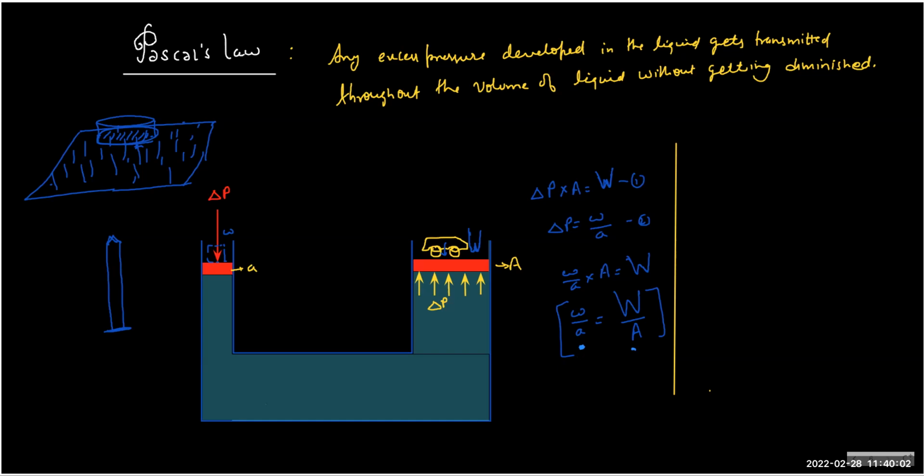It is very dangerous. In a pressure cooker, earlier there used to be a very large number of accidents. So later on, the safety valve was introduced. And what is the safety valve in a pressure cooker? Something like, you can see a hexagonal patch, and this part is very weakly welded with the lid actually. So if the pressure exceeds a certain value, this will be thrown away, and it will create an open hole, and all the gas will leak out and the pressure will drop.